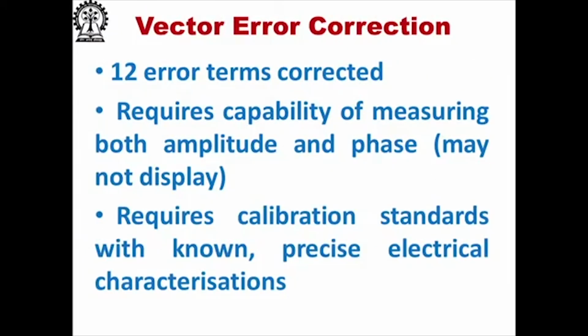Then you see that the time period for 1 kilohertz should be 1 millisecond, but it may not be 1 millisecond. So, you correct that. That is called calibration, that with a known thing you do. Here the known thing is some standard termination, then from that you estimate systematic errors, and in the actual measurement you correct for that. This is called calibration.